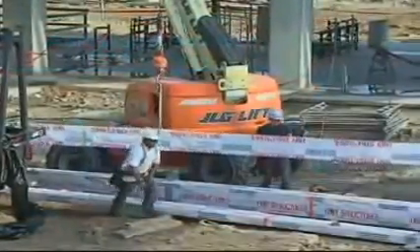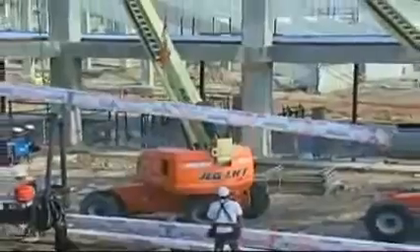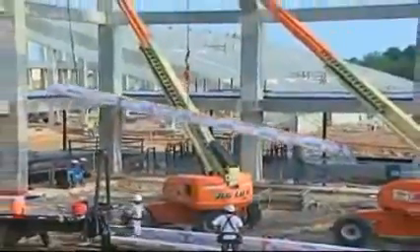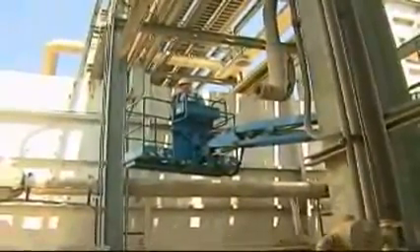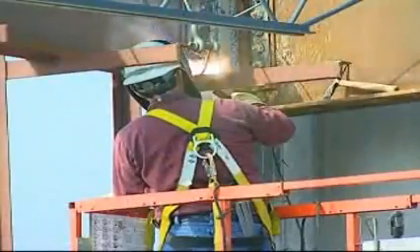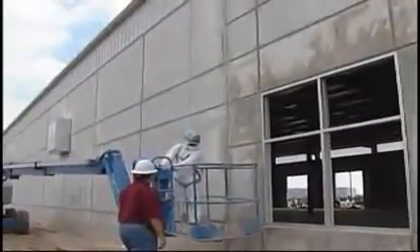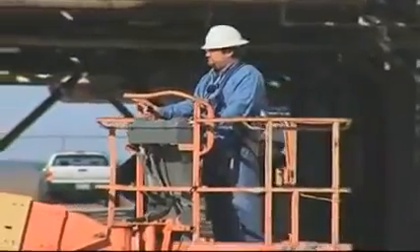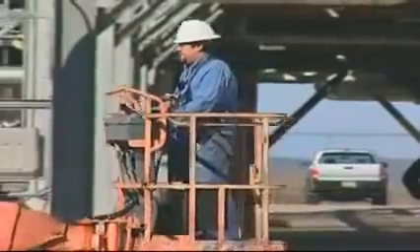Using a lift can be dangerous and risky. Lifts are a very useful time-saving tool in the construction industry today, allowing workers to get into areas otherwise inaccessible. However, lifts can be dangerous in untrained and unauthorized hands. Before you use a lift, you must be trained in its proper use. Always use fall protection while using a lift. Finally, if you don't understand any part of the lifting procedure, a lift's operation, or its safety features, ask your supervisor. The accident you prevent may be your own.